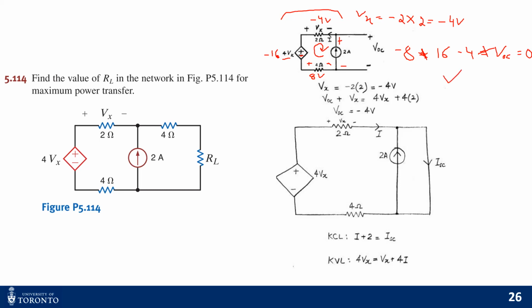Yeah, so this is plus, so this follows like plus VOC equal to 0, right? That's the actual KVL. So the VOC, if you take on the other side, it becomes minus VOC is equal to 4 volt. So basically VOC becomes minus 4 volt. All right. So now once we get this minus 4 volt, that's the VOC.